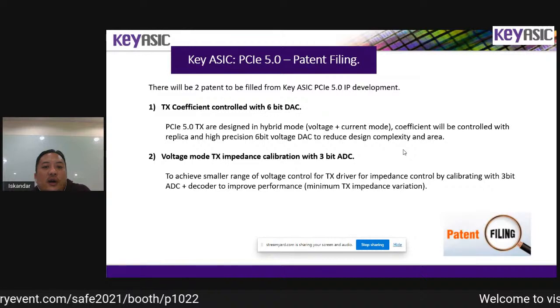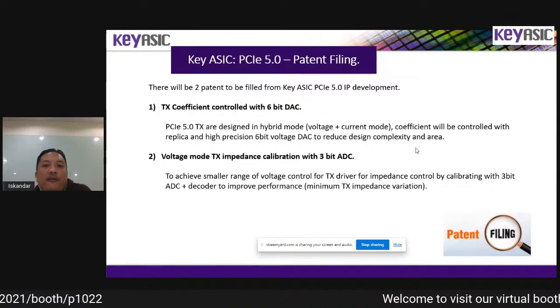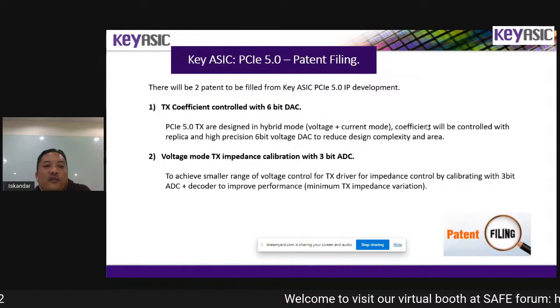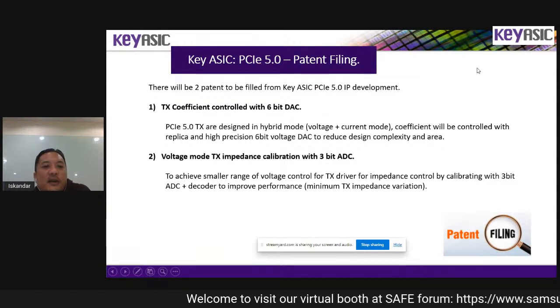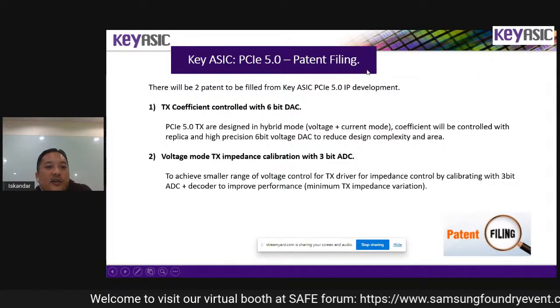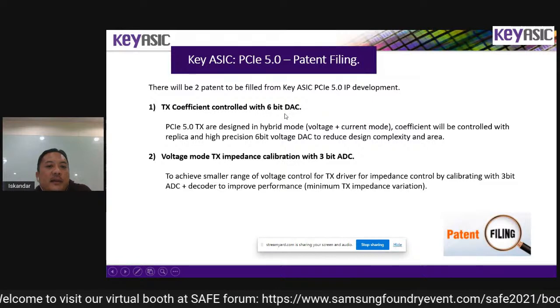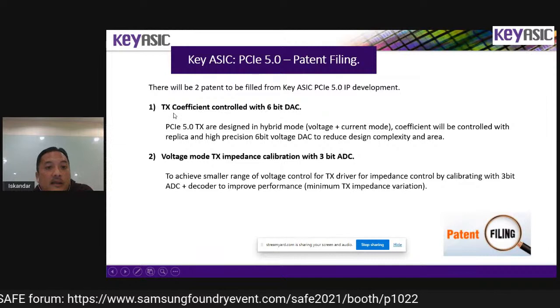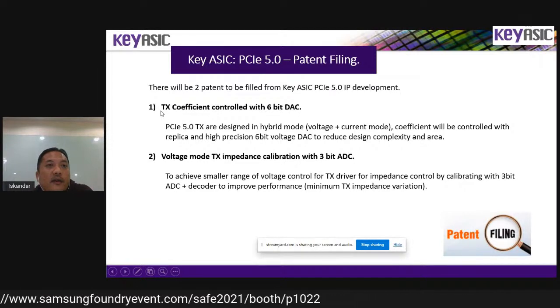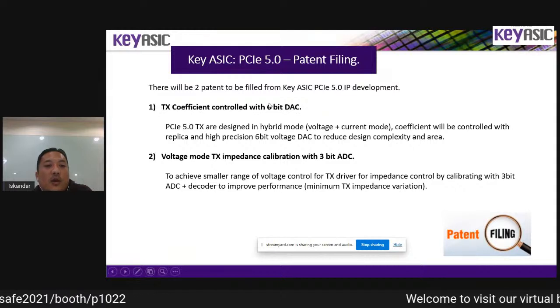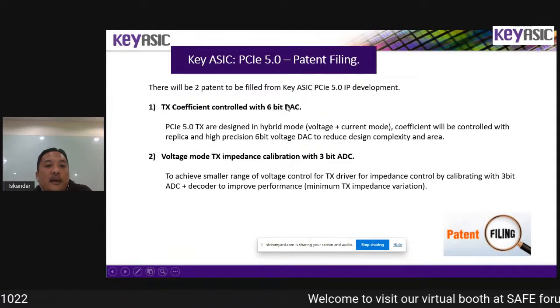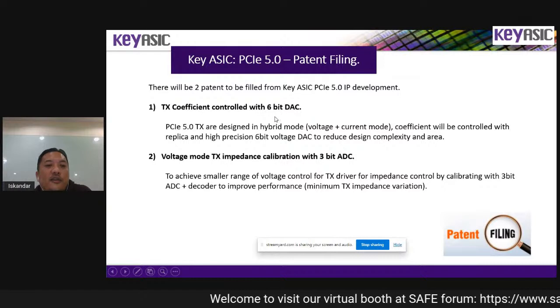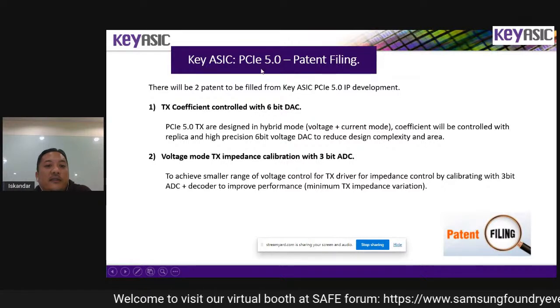So we have also filed so far two patents for this project. The first one is the TX coefficient control with the 6-bit DAC. Inside our driver, we have a current mode driver. So we use a 6-bit DAC to control all the coefficients that we have discussed in the previous slide.